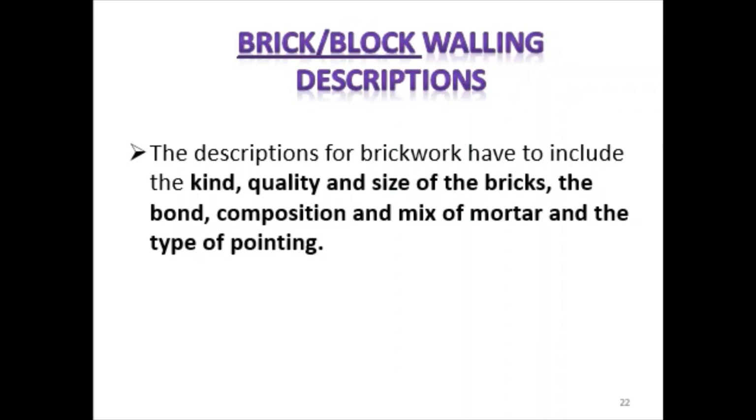Meaning you need to state, is it a block, is it a glass wall, is it a stone wall, and what is the quality and the size of the bricks. You should know the size of the brick from your drawing or specification, and what grade it is, whether it's spacing and so on, and the bond, the mortar joint, and the arrangement that I told you previously, and the type of pointing.